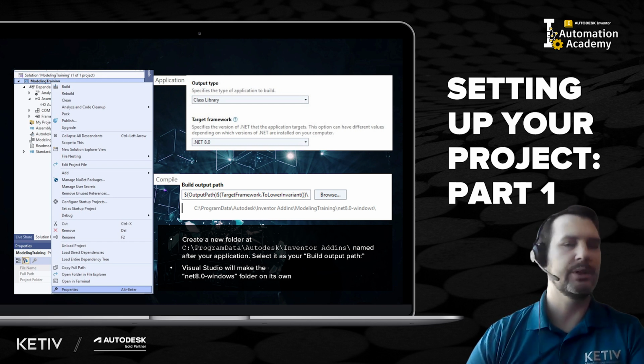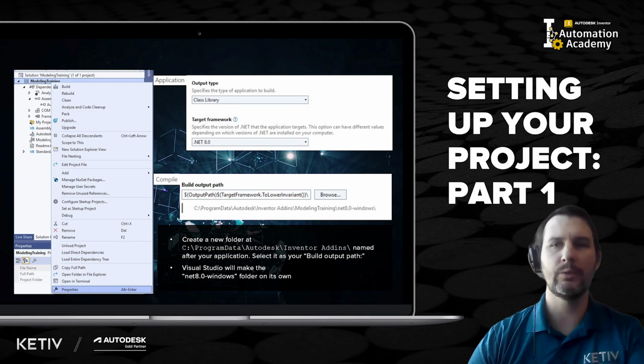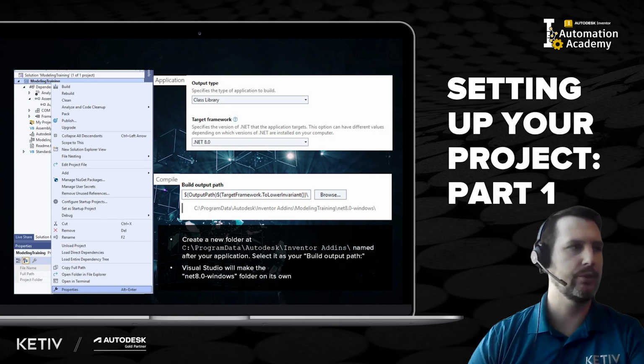Then we need to change the build output path. So this is where the thing will compile to. And so you can see the location that we're going to be using here. See ProgramData, Autodesk, Inventor Add-ins, Model Training. This .NET 8 Windows folder, it will create for you. So you don't have to do that.